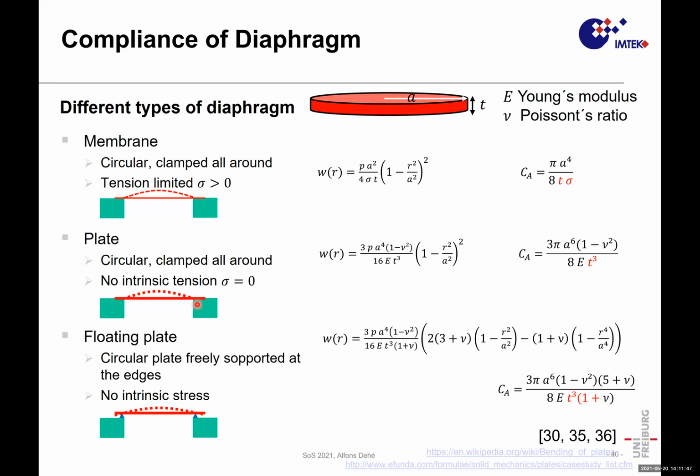If you have a clamping situation and you have compression from outside to your device, it will generate compressive stress in it. Or if you have tension, you include some stress to your device. If it is floating like this, it cannot react to external forces. So you have always ideally a free floating plate. So with this set of mechanical devices, we have diaphragm chances to transfer sound.